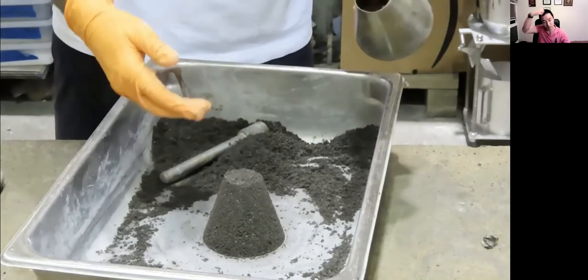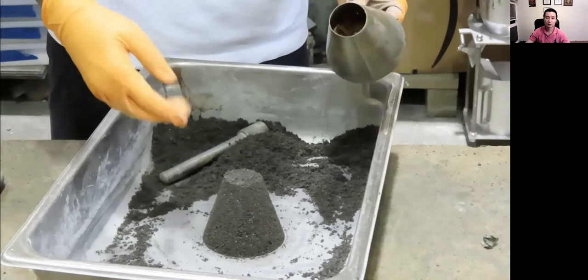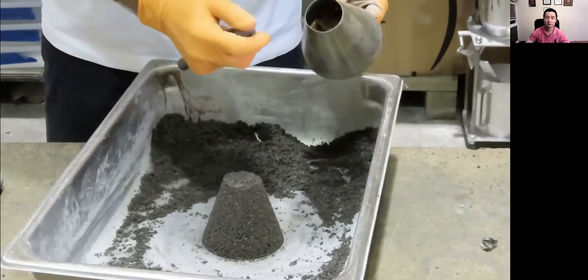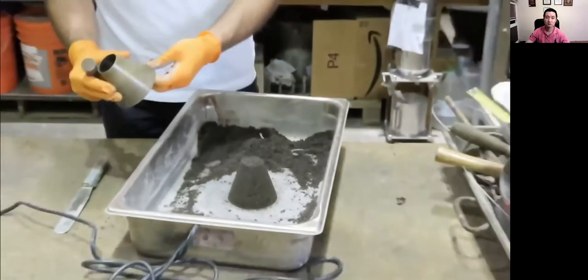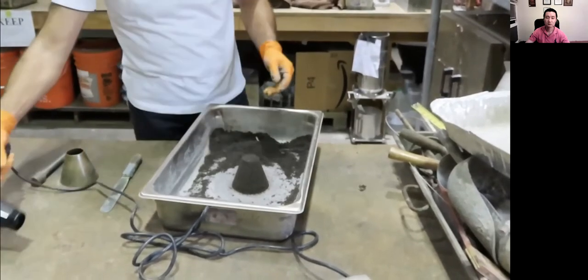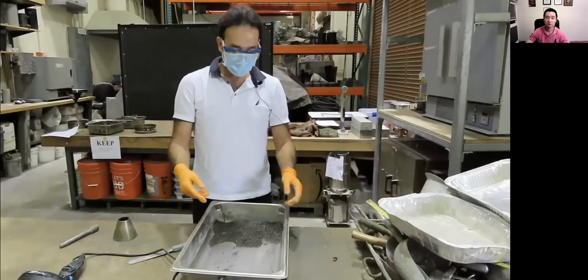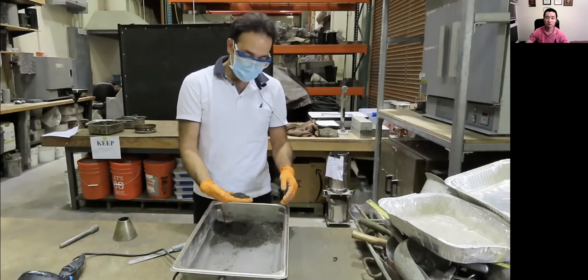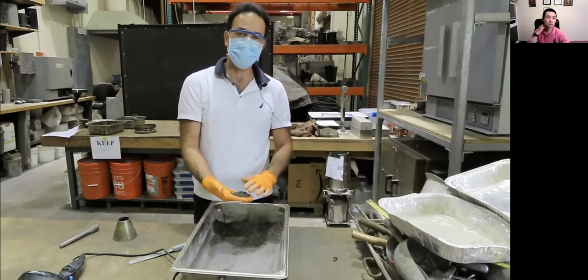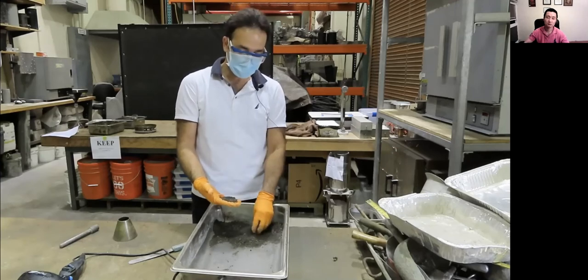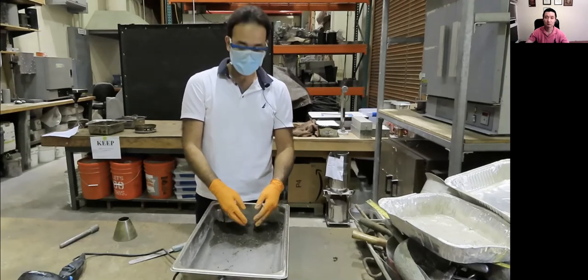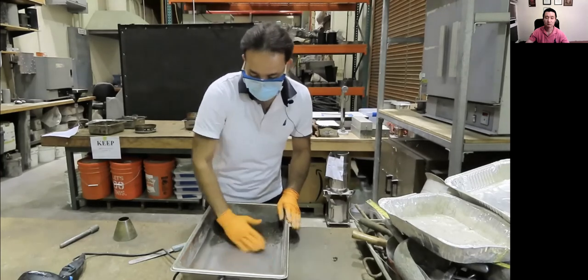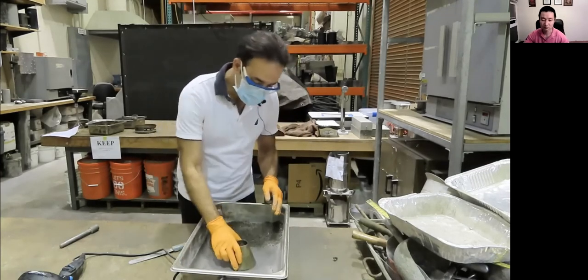It means that I need to keep drying and drying to make sure that all the surface of the fine aggregate is dry enough. Okay, I guess that the aggregate is in SSD condition, is dry enough. My reason is that the color turned into something lighter. The previous one was totally dark. I just try it to make sure that if it's in SSD condition or not.